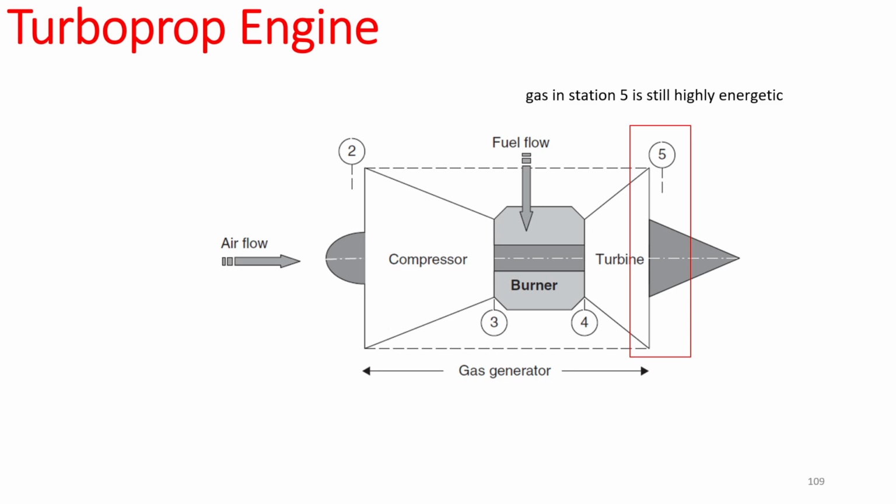So essentially what Ryan is suggesting is to add another shaft, which is going to get the energy out of the same turbine we already have, right? That is what you're suggesting, right? What else? Don't we need to reduce the revolution in order for it to use for turboprop? You're going to need a gearbox if that's what you're implying. Yeah, that's for sure. We are going to need a gearbox because we definitely have to change the shaft power to make it suitable to a propeller, right?